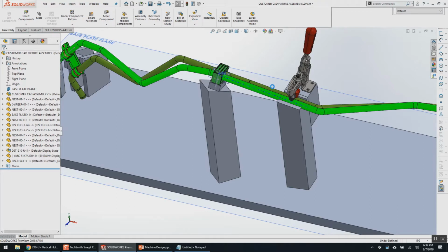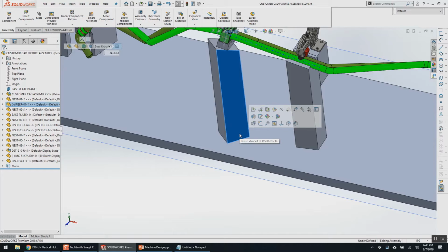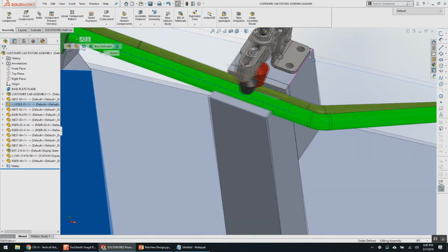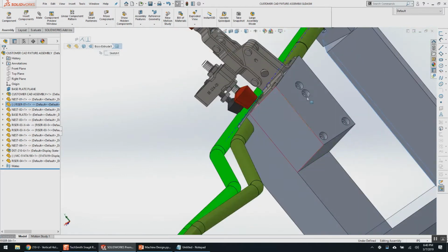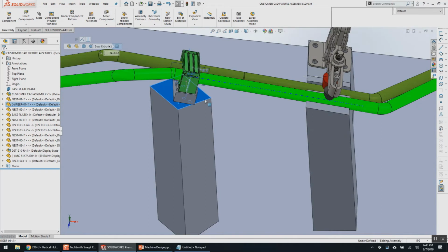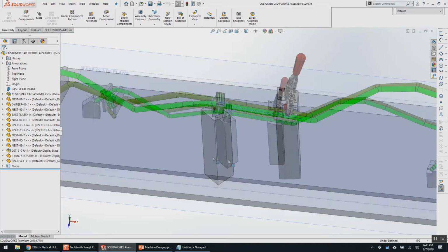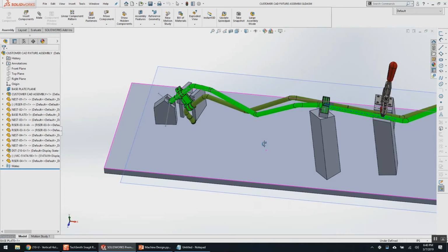And this is pretty much the level at which I finish the design. I know for a fact that I can put holes in the bottom here and they'll go through the plate. That's not a fit, form, function problem. The more challenging questions: do I have room for the Destaco clamp? Are the holes that are holding this block on hitting that? Can I fit holes in here? So I'm putting holes in the design where necessary to validate the design at its current stage, and I'm not putting holes in stuff where I absolutely know, beyond a reasonable shadow of a doubt, they're going to fit and I'm not going to have any problems. So if you're asking why I'm being so eclectic with my hole placement, that's the answer.